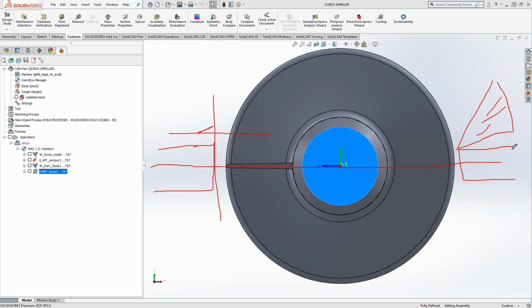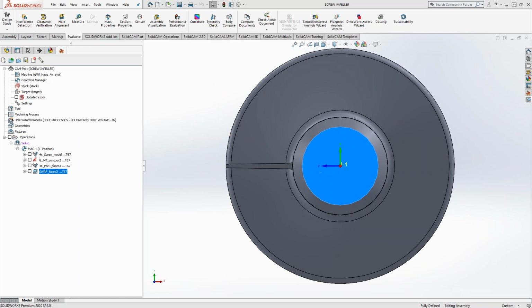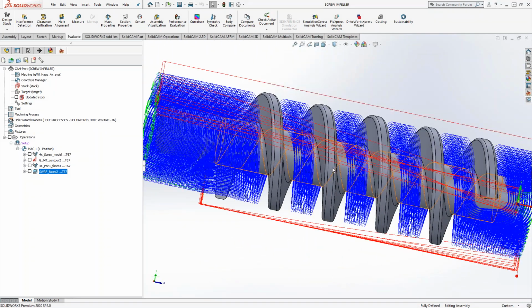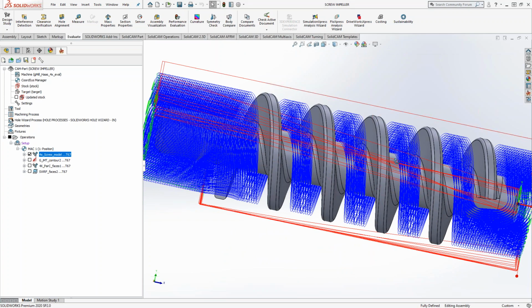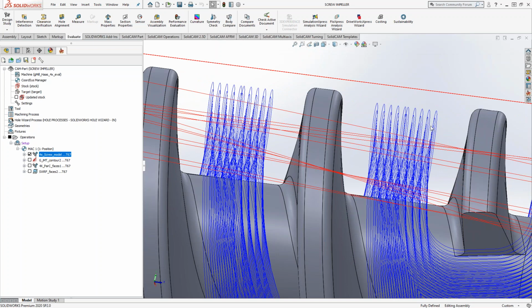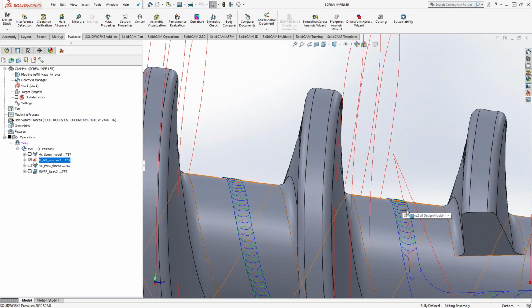So if we were to compare the screw machining, let me just erase all this stuff, to the iMachining, you can see there's a little bit of a fanning out there. You can see that the tool does go a little bit radial. I mean, obviously there's a step over, but I'm talking about how far away from center this thing gets to go. Whereas with the iMachining, if we see the tool, that's the center line of the tool. It has to be straight up and down.